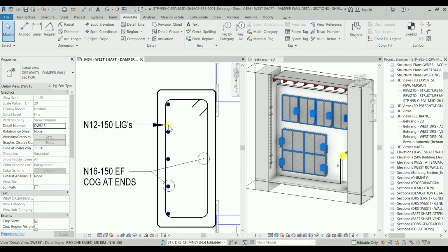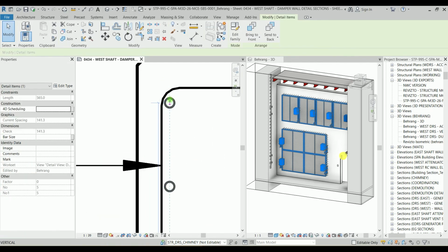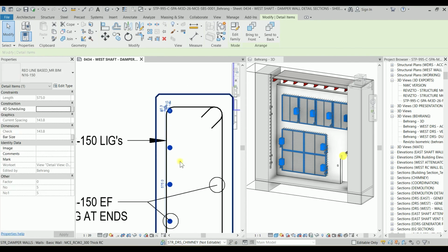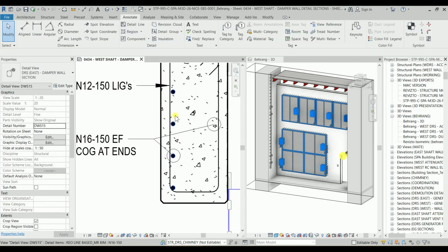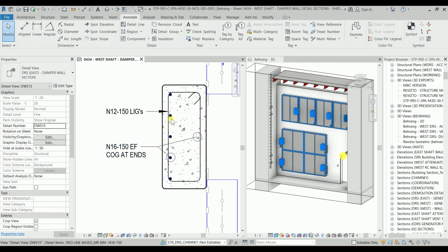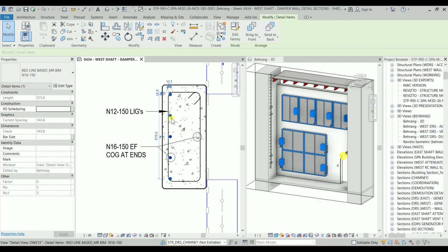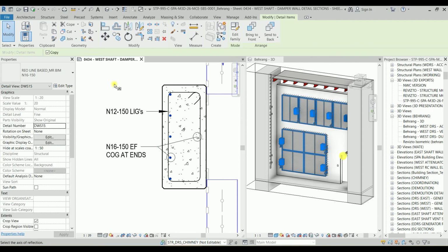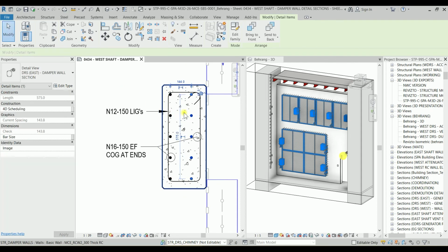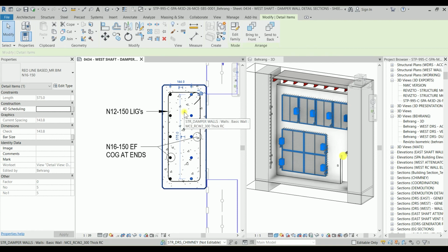I'm clicking here, and I'm just clicking here. So now I can just fix it there and there. Now it's just beautiful. So I will click on it and type MM for mirror. I will mirror it to this axis. It seems that it's not correct, but anyway, I can just nudge it to the other corner.